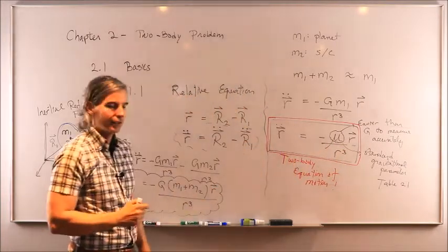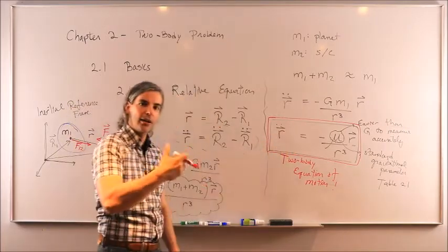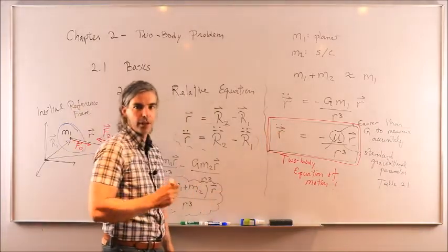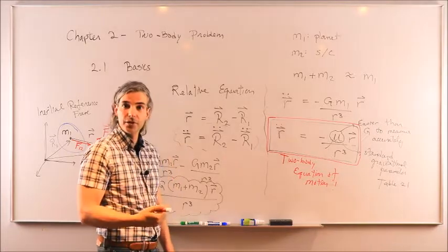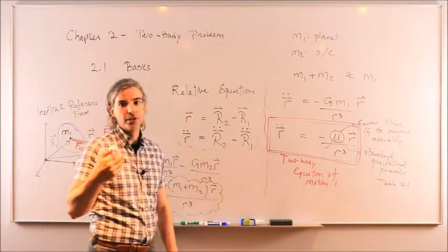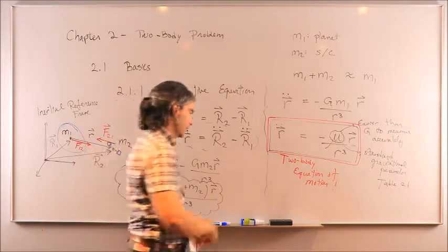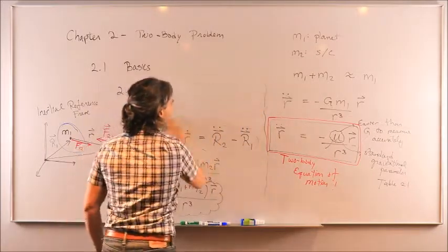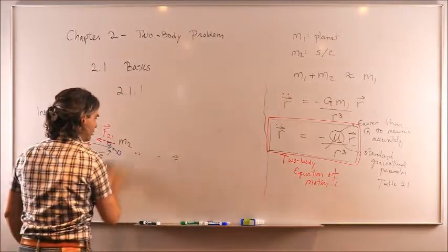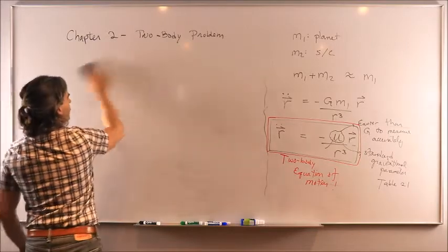what acceleration it is experiencing. Furthermore, once you've calculated the acceleration at each time step of the process, you could go and integrate this value at each time step to obtain the velocity of the spacecraft on orbit. And then integrate again to get the position of the spacecraft at each instant while it is orbiting. Okay, so in other words, it's very simple. Okay, it doesn't get any simpler than that. So this very simple equation of motion allows us to completely describe an orbit.